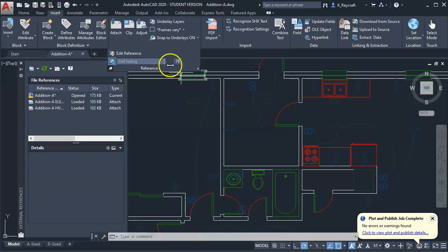You can see as I drag my mouse to the right, it becomes fainter or more brilliant. It's just a really good way of being able to visually tell whether something is a part of the drawing because it was drawn in the drawing or whether it's an external reference. I'm just going to set that back to 50, which is very painstaking. That's good enough.